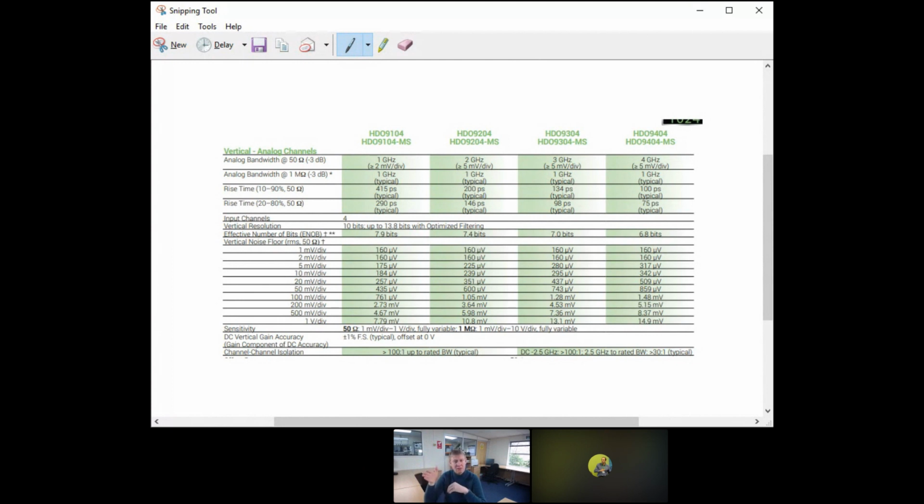Then the internal amplifiers in your oscilloscope have to come out of saturation to be able to then report the voltages at lower levels, and that takes time to do, and that's where things like the circuit you showed, Jose, that clipping circuit which isolates the front end of the scope when the voltage exceeds a certain level. That's why those sorts of systems are really useful, because it means you can then dial in the accuracy you need on your scope without having to worry about amplifier saturation and things like that.